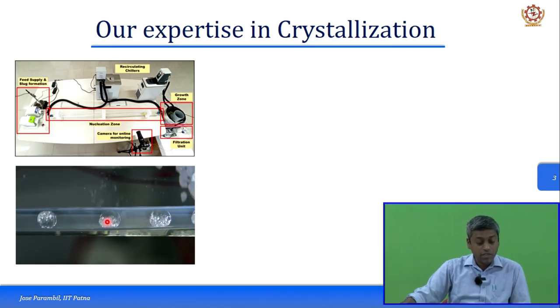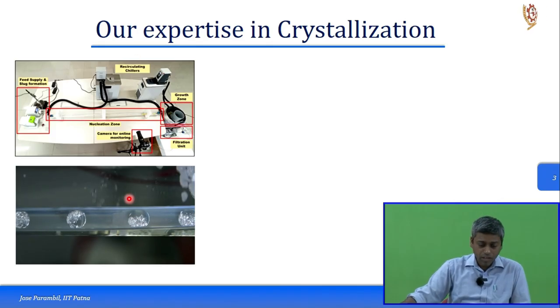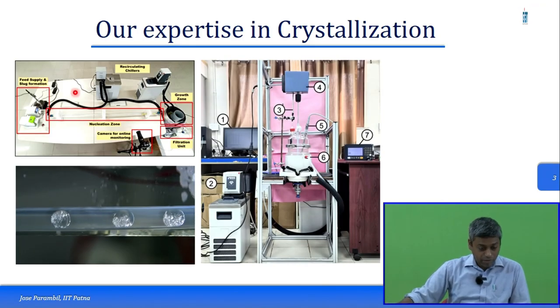The crystallization occurs inside these slugs, and by changing the flow rate, temperature, concentration, etc., we can modify the crystallization behavior. We can produce a specific size of crystals, get a specific purity, and change several parameters by controlling various operating parameters on the crystallizer. So that is one of the studies, and this is a continuous crystallizer.